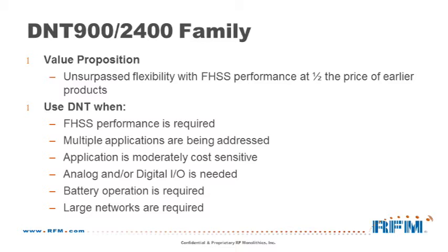When multiple applications are being addressed with the configurability in terms of RF data rate and power, one design can work for a number of applications. And it's been interesting to me, the number of customers that we have that really weren't sure how much RF data rate they needed. And so they've been able to look at it and say, well, does it work at 38.4 kilobits? No, that's not enough. Then I'll bump it up to 115 too. But they have the ability to play with that, and it also gives them some future proofing with the higher data rates of 200 kilobits per second and 500 kilobits per second to add more features and functionality.